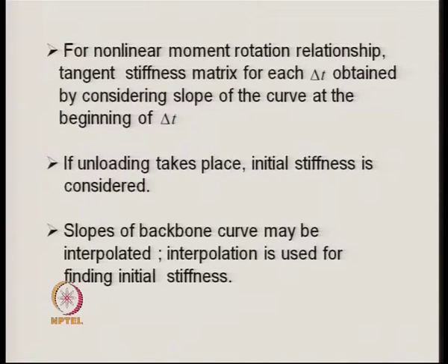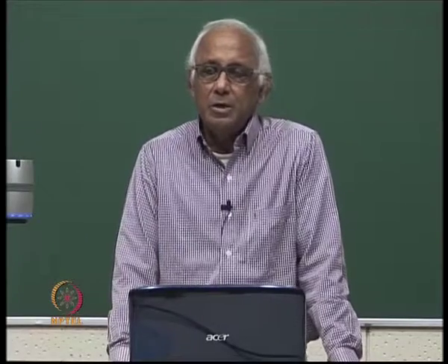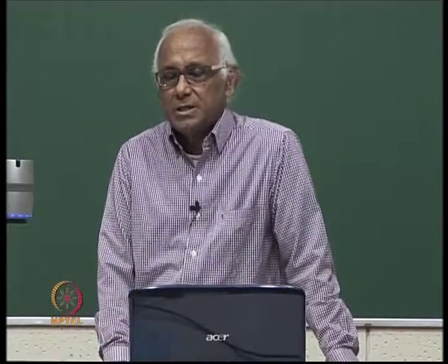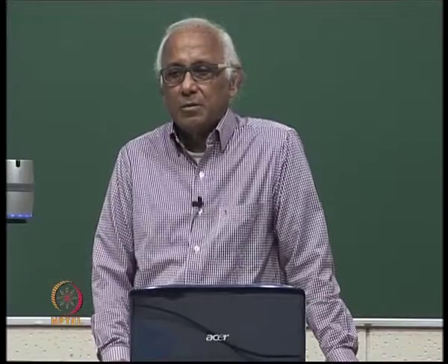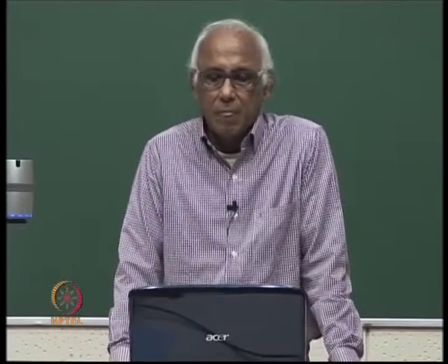Therefore, as we find that there is an unloading for a particular element at a particular cross section, then in place of taking the tangent stiffness for that time interval, we consider the initial stiffness for that particular element and go ahead with the calculation.